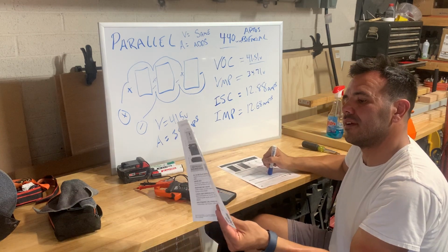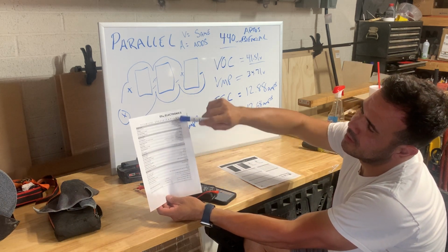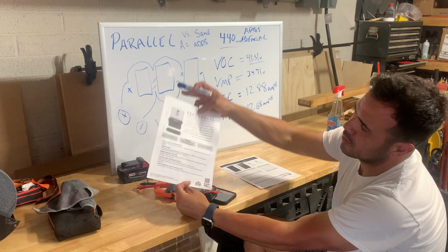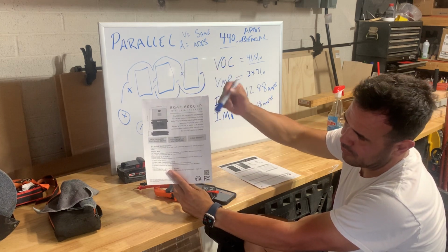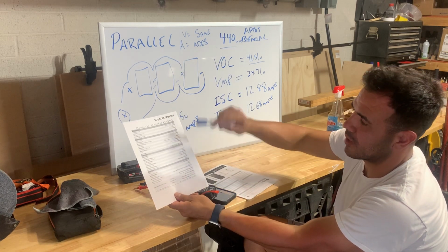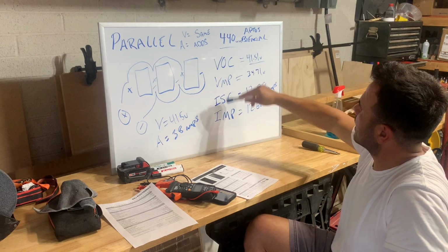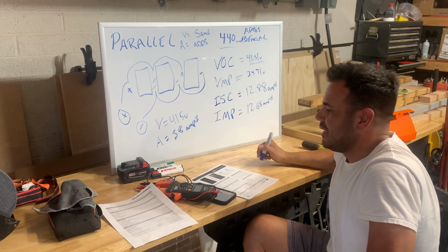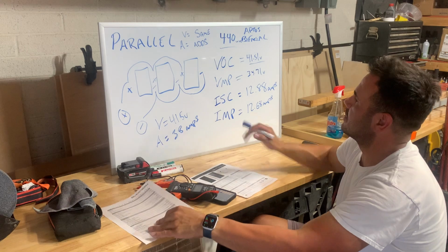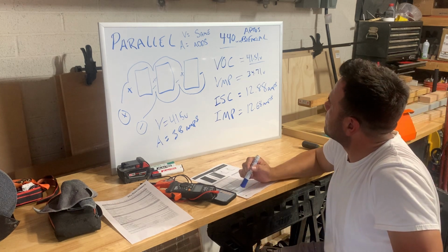Because in the next video that I do, we'll go over the inverter and exactly what the PV input specifications are. Like what's the range of voltage that you need in order for this inverter to turn on, and what's the maximum amount of voltage that this inverter can handle before it starts to damage the components inside. When you look at a spec sheet, it's going to tell you the ranges, and you're going to be able to calculate those ranges based off of your solar panel specification sheet. And that's these figures that we went over. So I'll end this video here. On the next video, we'll go over the inverter and we'll take this information that we learned here and see if we can apply it to the all-in-one inverter.